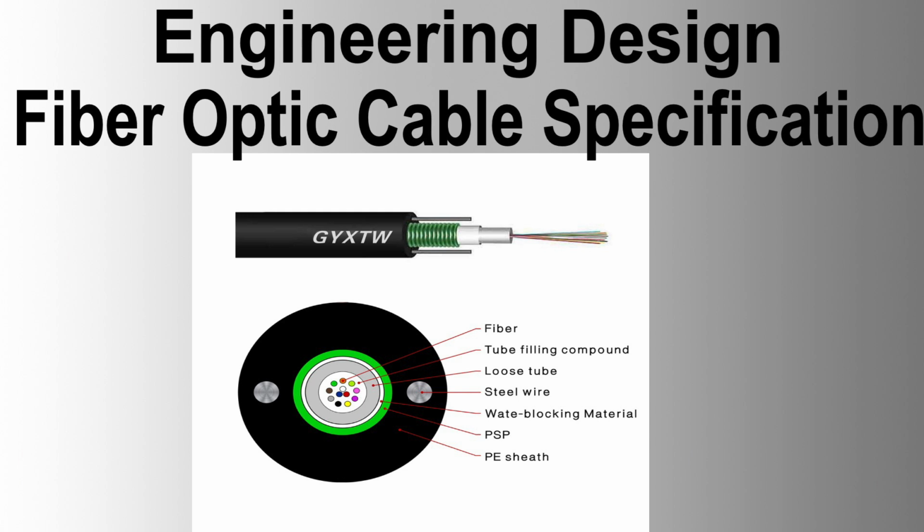Manufacturer's instructions. The contractor shall follow the conduit coupling manufacturer's instructions for the preparation of the joints and the selection of tools. The conduit ends shall be inspected, and only if no scratches or any other damage is found can the conduit ends be jointed. Cleaning. The contractor shall clean the conduit sections before joining them.